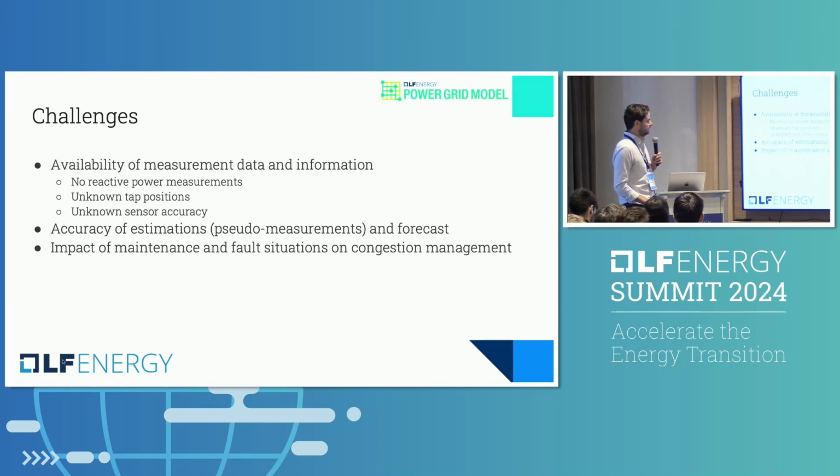What are the challenges that we're facing? Availability of measurements and other information as well. First of all, as I mentioned before, usually we don't have reactive power measurements as a DSO. Tap positions might be unknown or registered wrongly, which results in really different voltages in your calculations than what is actually happening in the grid. Unknown sensor accuracies.